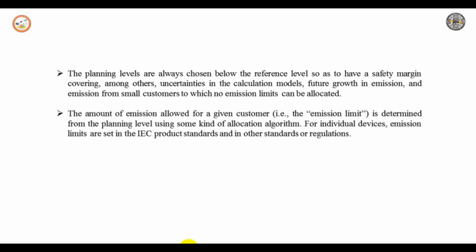The first change in the emission takes place at frequencies that were not concerned before: the interharmonics and even harmonics. Here, high frequency harmonics and slower voltage fluctuations. The reference levels for these are either low because it was easy to reduce the emission, or no limits exist at all because the disturbance was not seen as a concern.